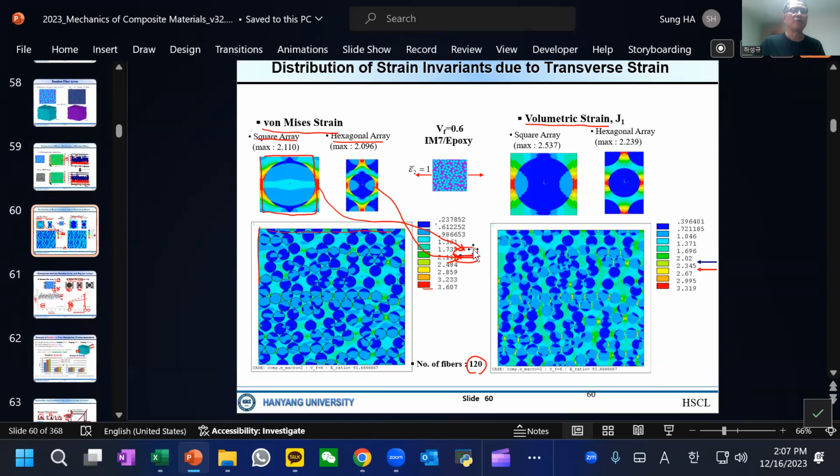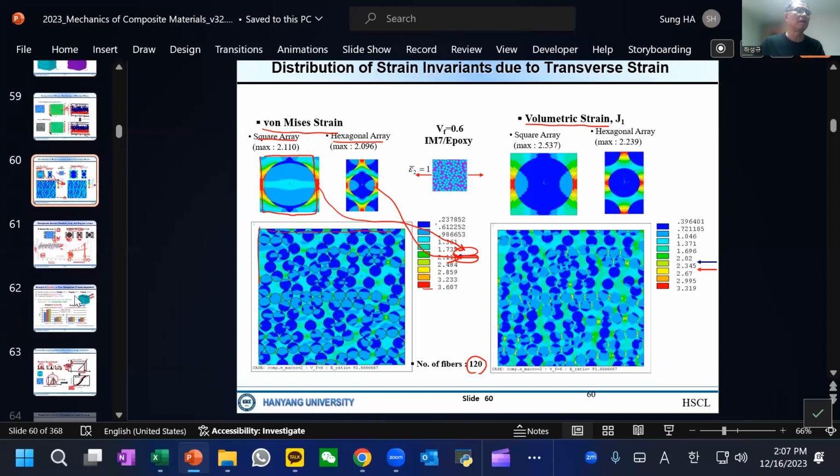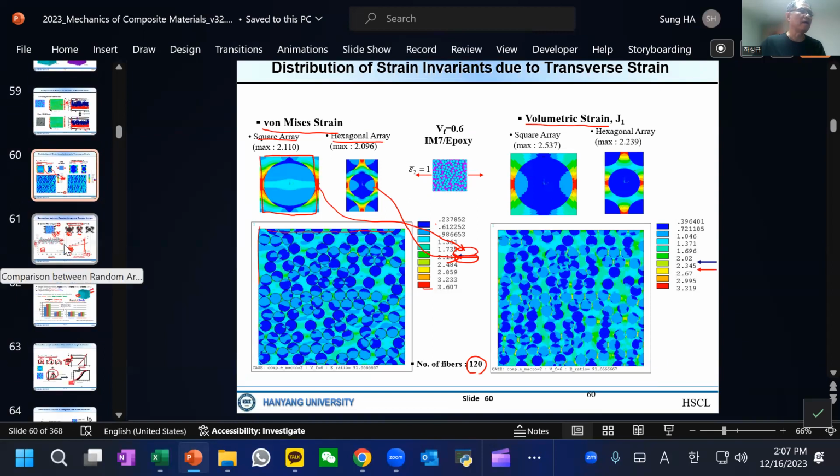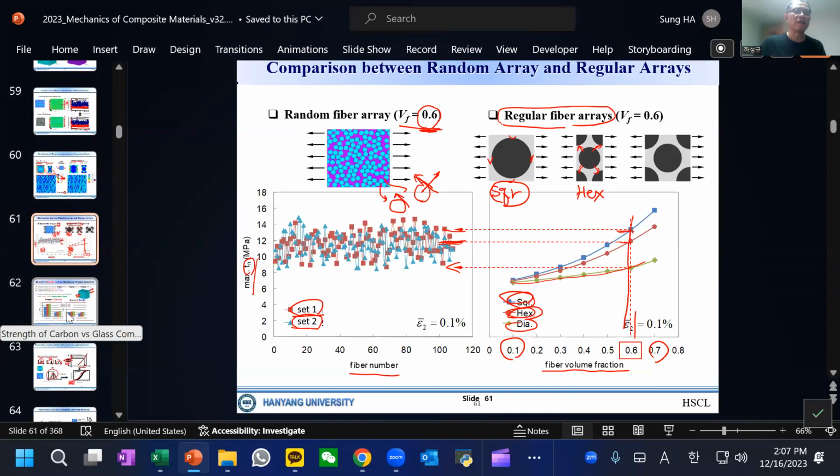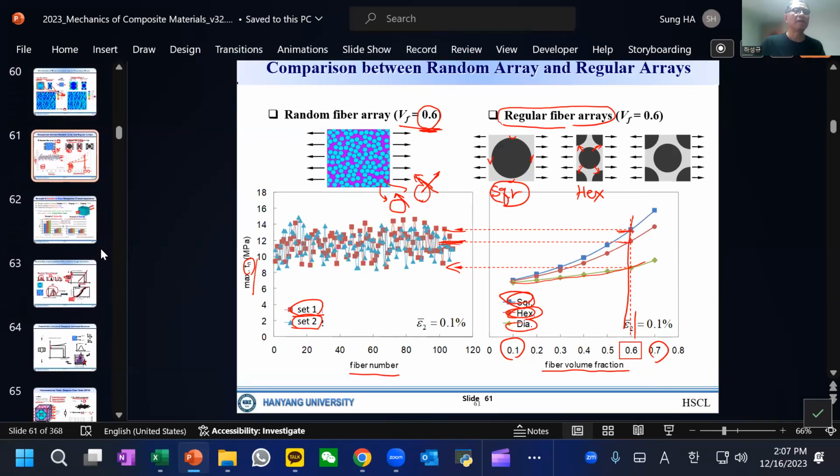So using this kind of random generation, we can understand the resin failure and fiber failure, and even fatigue, and the effect of the fiber volume fractions, and we can do a lot. And again, the main advantage of this micromechanics is that, rather than performing all the tasks on the UD composite, all you need to do is understand the resin and fiber.